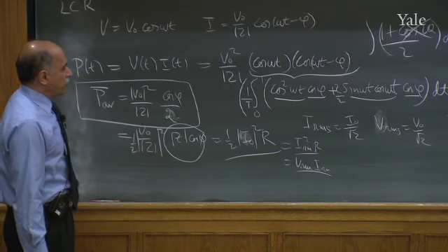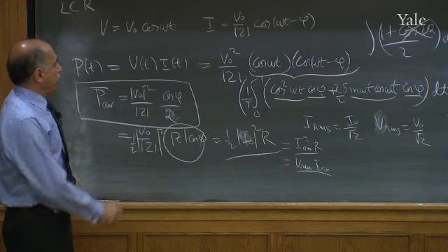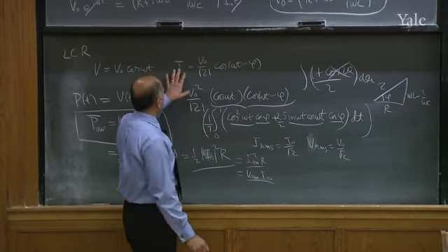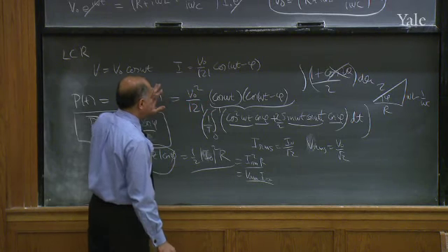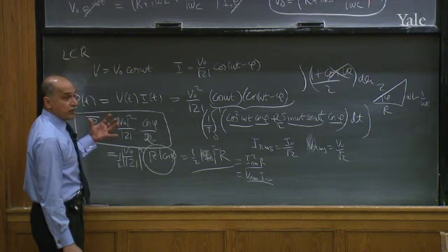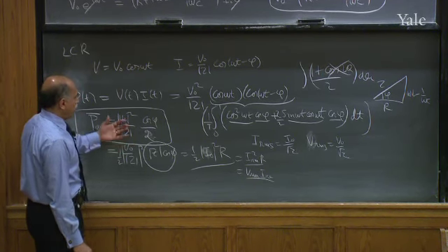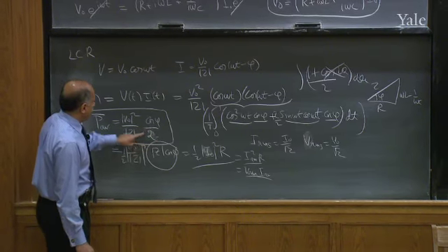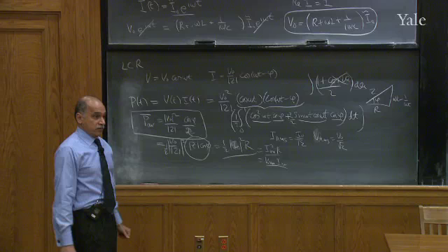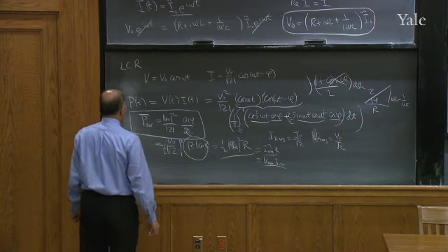Now, RMS means root mean square. There's a reason why for a trigonometric function it's got a number which is 1 over root 2 times the amplitude. But I don't want to go into that because we don't use it again. Main thing to know is if you want, you can redefine new quantities, V naught over root 2 and I naught over root 2, so that these factors of 2 disappear and things look like the good old days of resistive circuits.